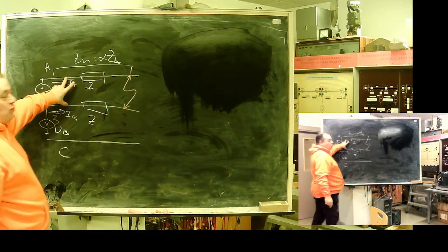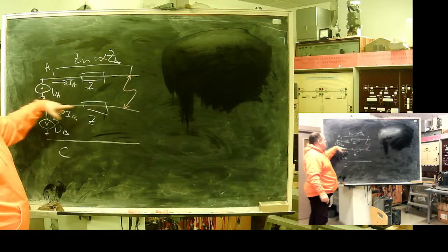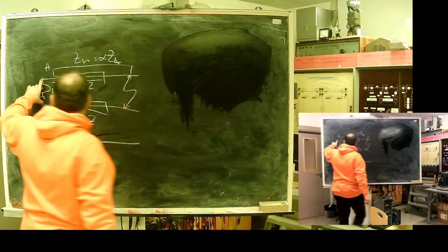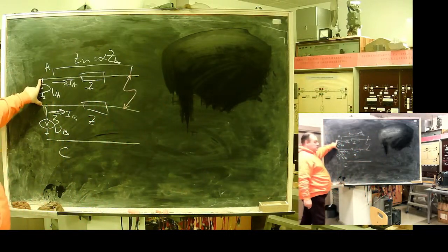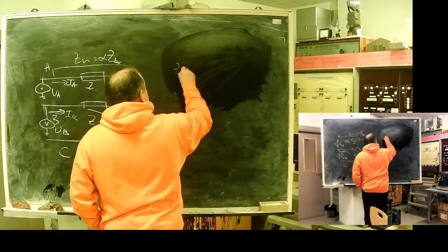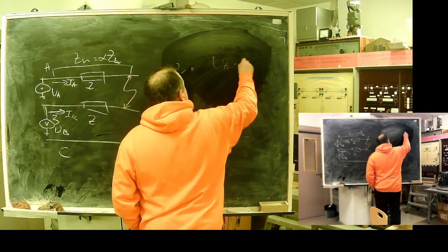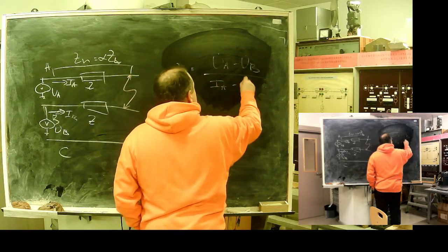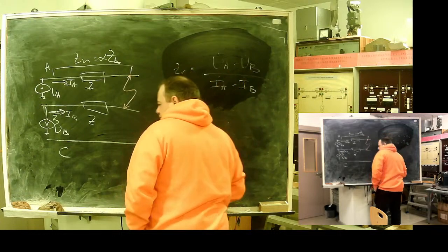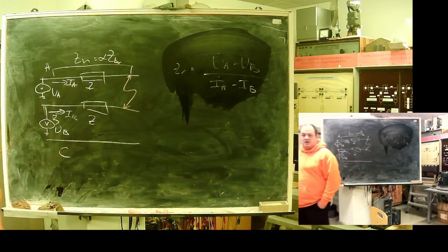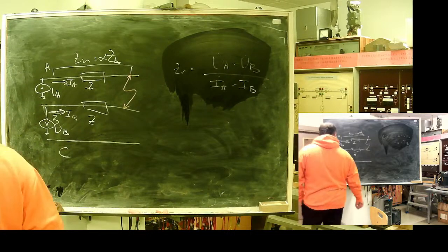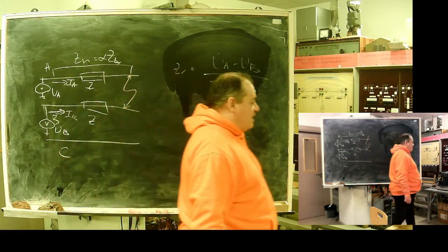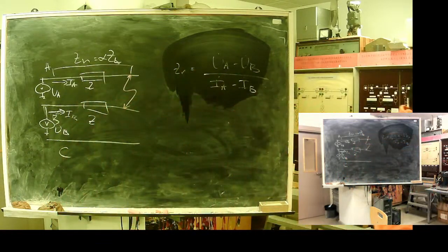Here is our fault loop. Current goes, current returns. So this voltage is UA minus UB. UA minus UB divided by this will give us the necessary resistance. Phase to phase voltage divided by current difference.